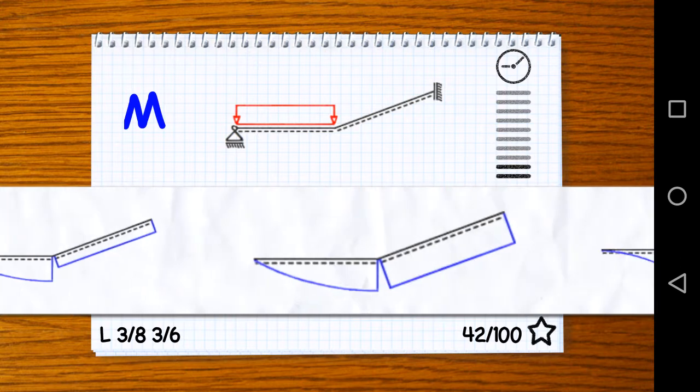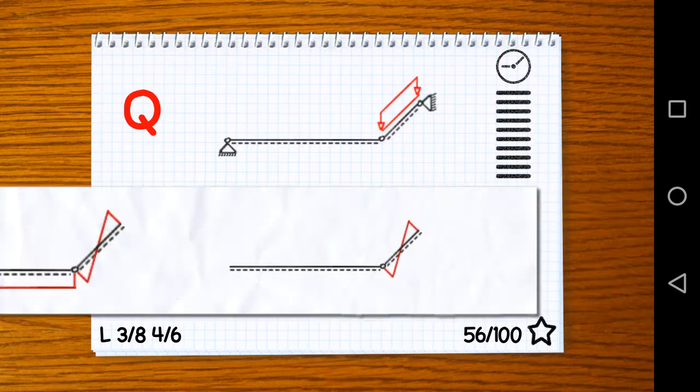Now, which one is it? It's this one here. Why? Because passing through an angle, the value of the moment doesn't change. In the left case, it would have changed. It doesn't change, except if you have a single moment, but it wasn't the case there. So what's going to happen here? This could actually be a truss. It's not completely a truss, but it could actually be considered as a truss.